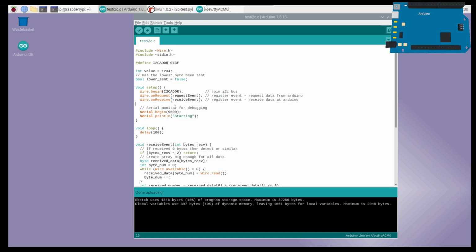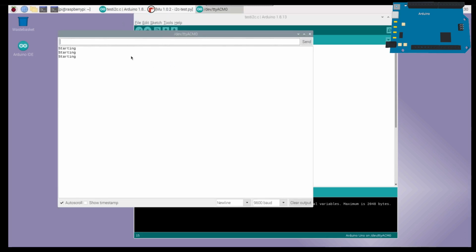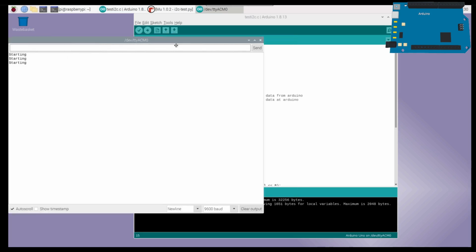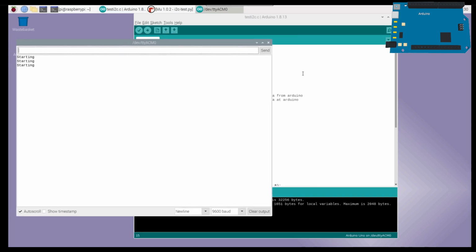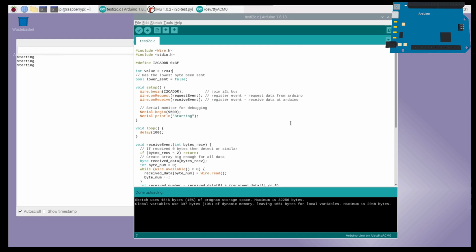The Arduino is set up to use the USB connection for debugging, so we're going to use that instead of having to set up the UART separately. It'll just go over the UART, which is built into the Arduino and communicates with the USB. I could use Minicom, but I'll be using a console here, which is part of the Arduino IDE. So I'll just go through the code.